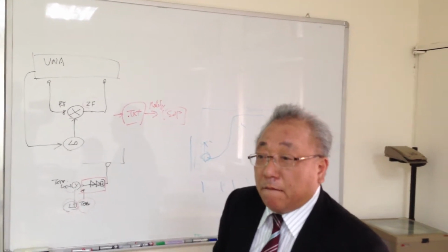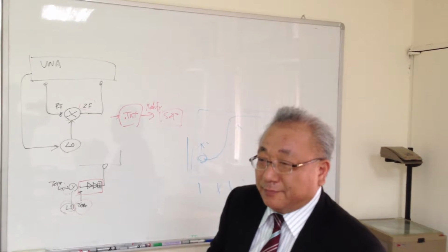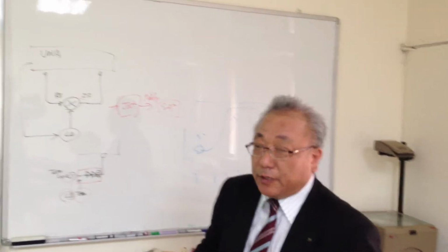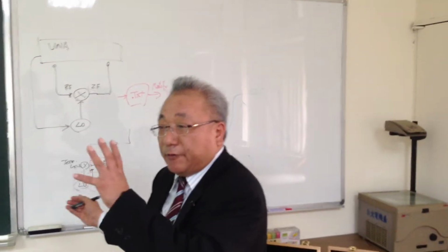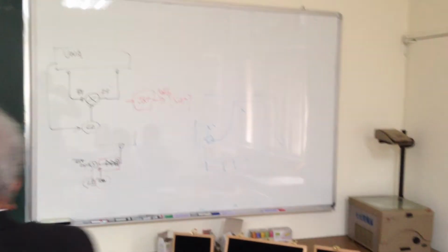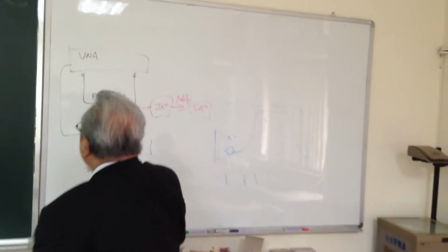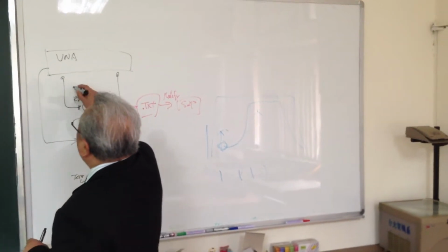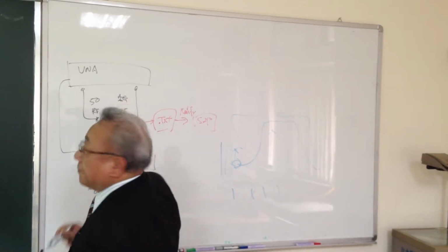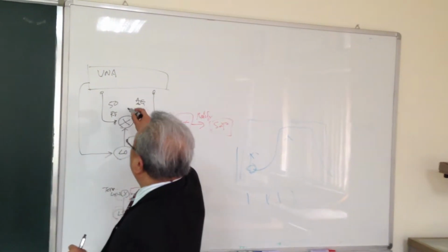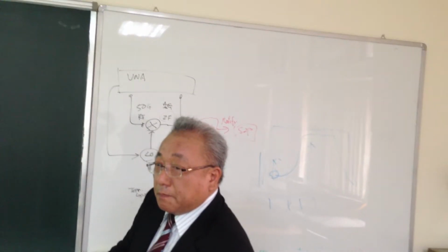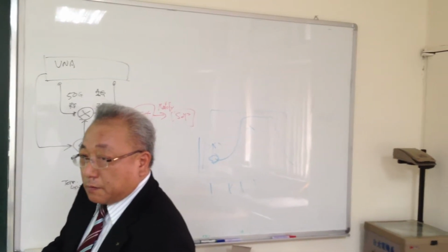So which frequency do we need to calculate, the RF frequency or the IF frequency? It depends on your device. We have no limitation for the RF input and IF output. If we have maybe 50 gigahertz RF and 1 gigahertz IF output, should we calculate all the input and output from 1 to 50? Cover all of the IF and the RF frequency? Or only IF?